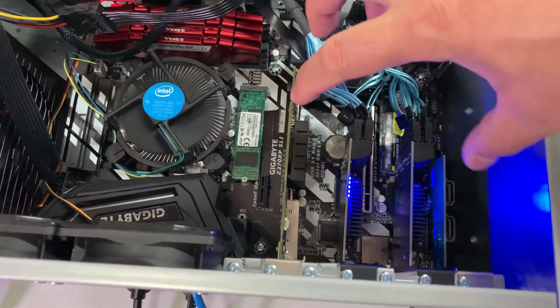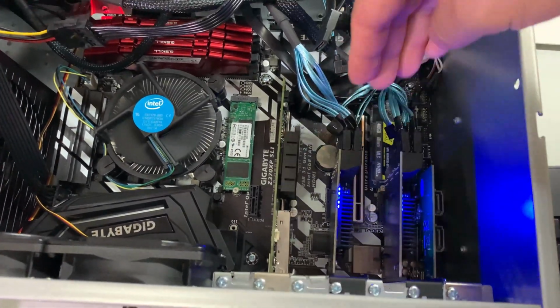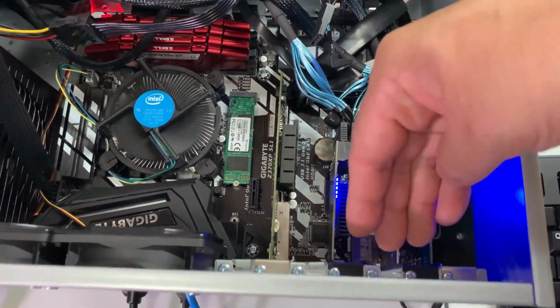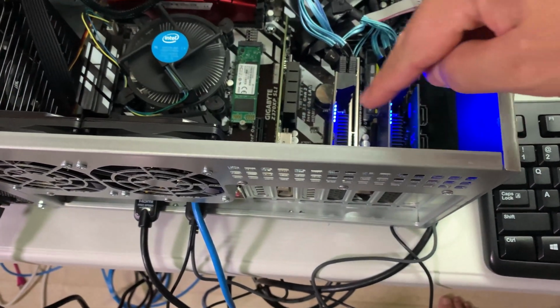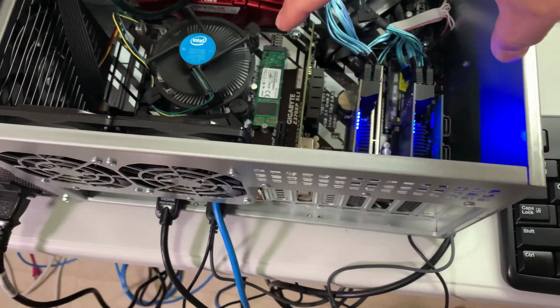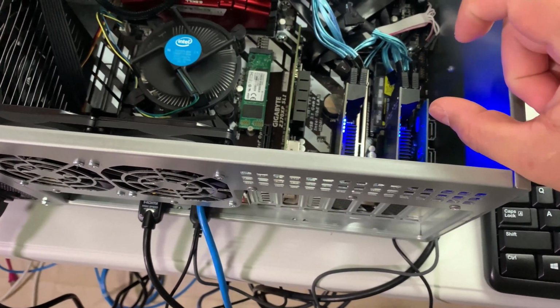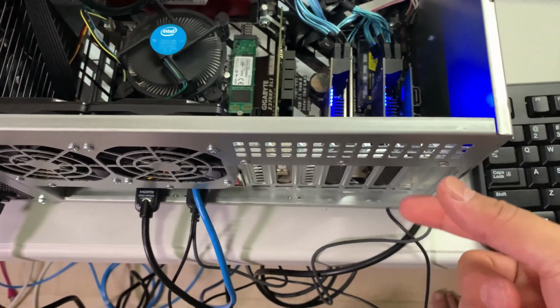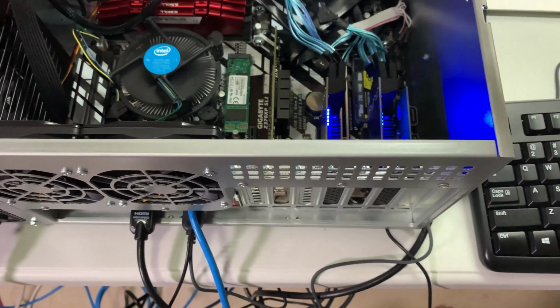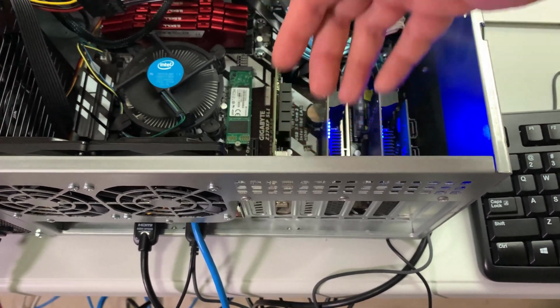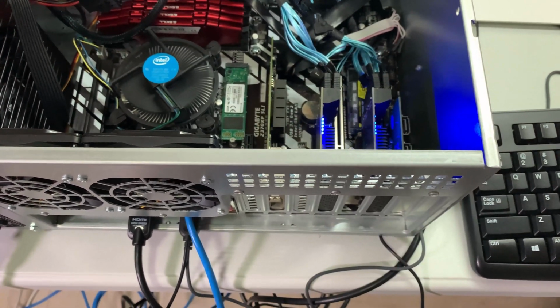So I plan to have an exhaust fan to suck the hot air, so at least there is also a convection current to move hot air out of the chassis through the exhaust. So I've ordered a 120 by 30 blower fan, that means 120 wide plus thickness of 30 mm. Right, here is also probably about 30 to 35 mm, so I have enough space, and that will help to draw more hot air out of the chassis.